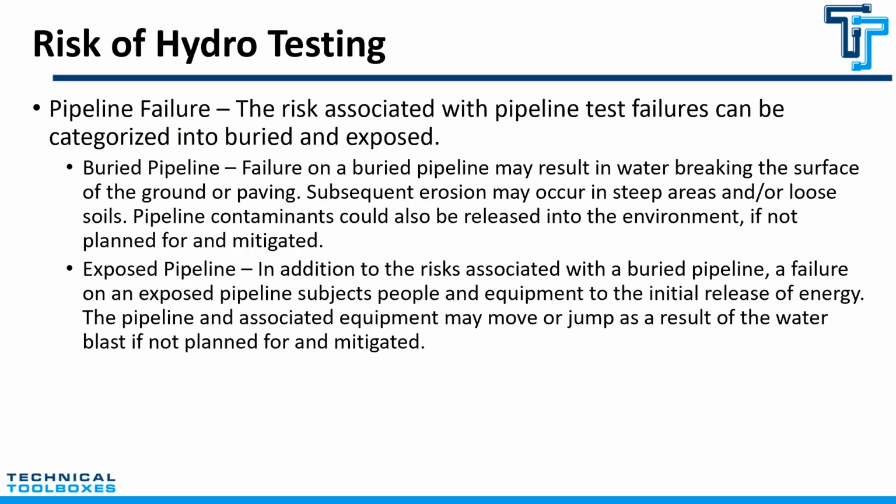There are some risks tied with the hydrotest, so we want to break it down to discuss hydrotest for buried pipeline and exposed pipes. For buried pipes, the risk is lesser compared to exposed pipe. Exposed pipe has everything you see as concerns with buried pipe, and the additional aspect is that you are now exposed, which really affects the equipment and the personnel doing it. So it comes with its own consequences and failure. A good plan should analyze the consequences tied to a failure too.